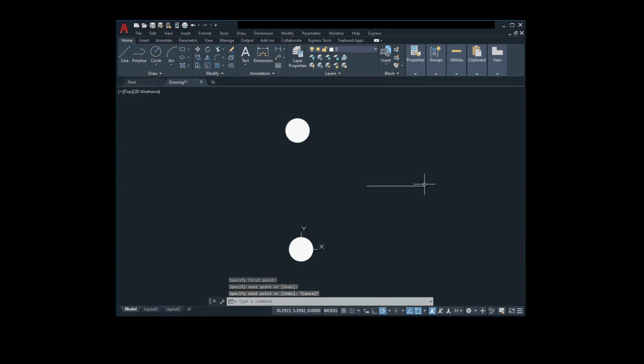So here's a line, and what if I just type in donut, specify, let's see, I'll do 0, I'll do 2, just keep the same one. I can snap to an endpoint, I can snap to a midpoint. Well, let's do midpoint. And there it is. And I hit escape to cancel the command. Now donuts are used to represent O-rings, washers, but if you're doing architectural, maybe this is a top-down view of a column of a building. So this is an example here of a filled circle.